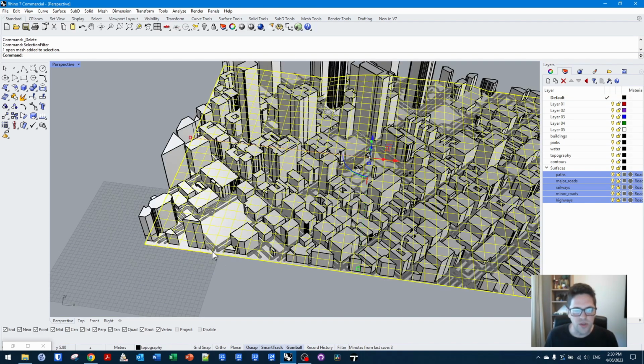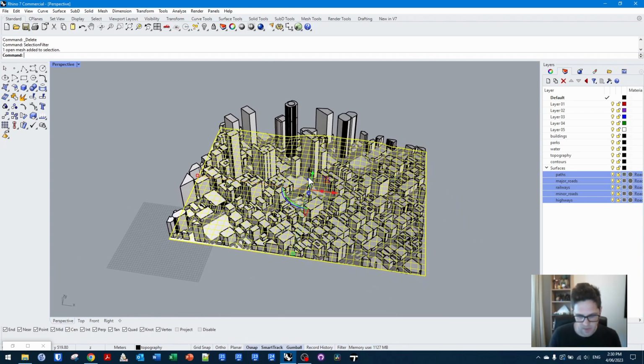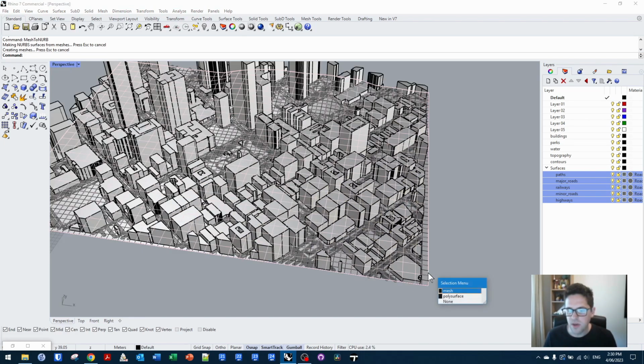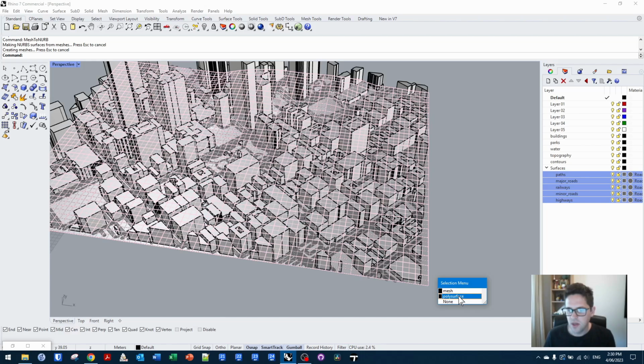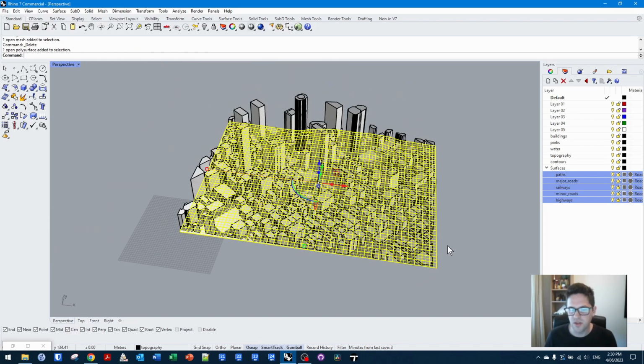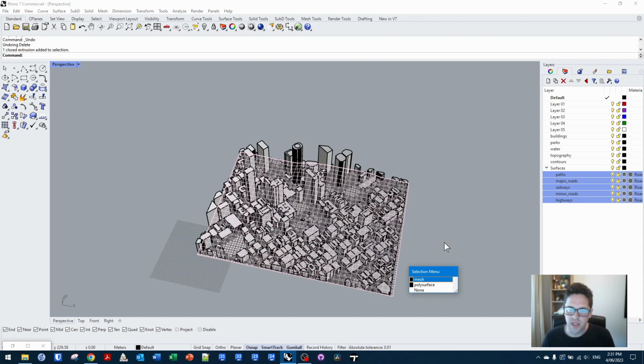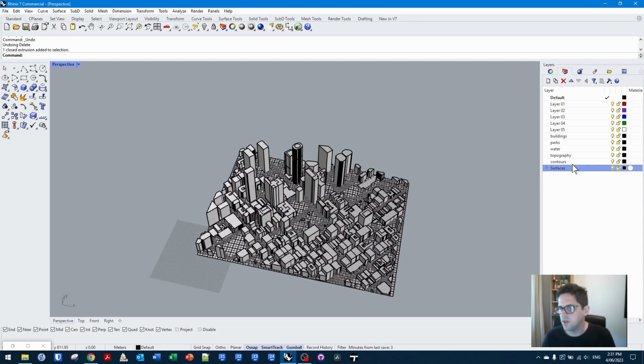So typically you should also get a mesh for your ground surface. Typically I recommend using mesh to NURB to turn this into a BREP. It's a more processable object. You can keep the base mesh if you want, or you can just leave the poly surface behind. But this is good if you need to do a split operation on the ground. Sometimes this is a much easier thing to work with. I may actually keep both in this case because I'm probably going to use the mesh to run a mesh ray later on.